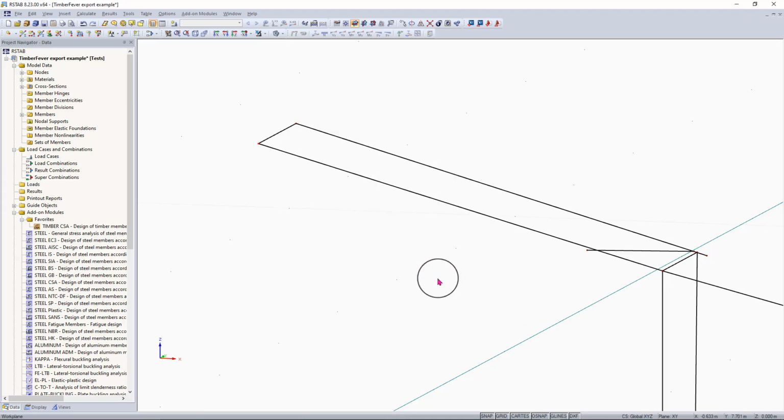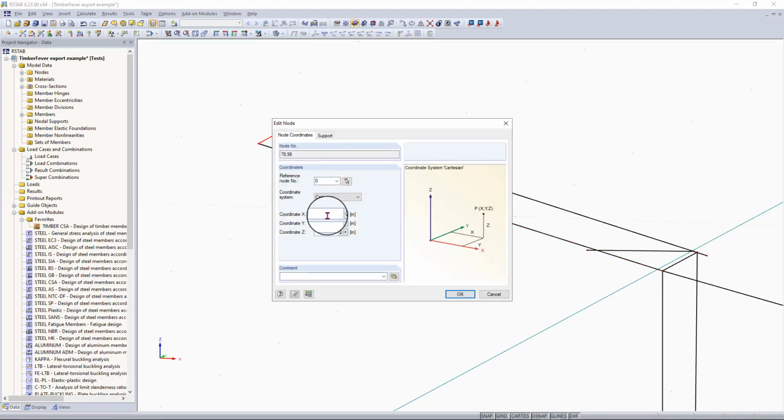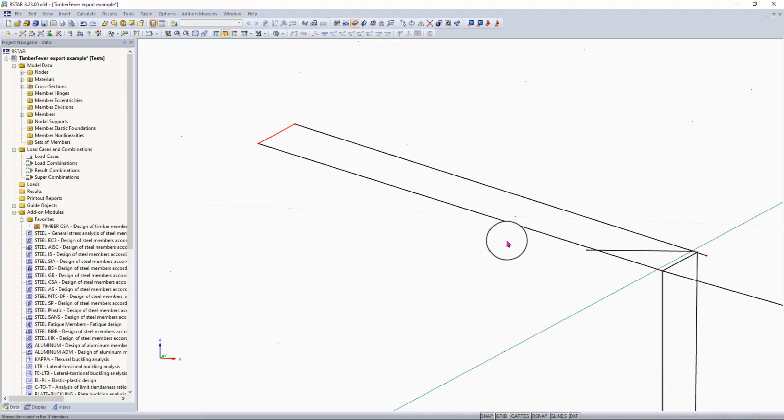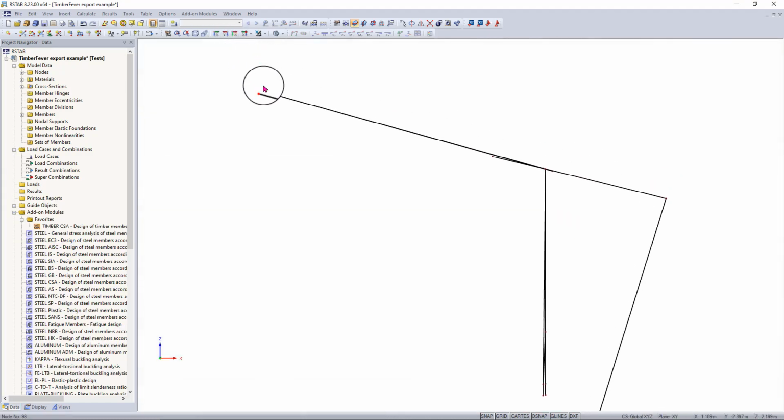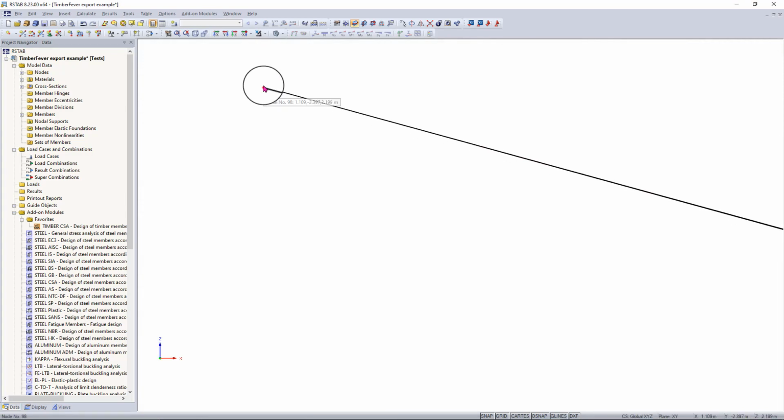We can click OK. Then what we can do is drag from left to right to highlight two of these nodes. We can double click on them, and then we can type in those coordinates. So 1.109 for the X and 2.199 for the Z. So now if we look at our view in the Y direction, we can see that our nodes are completely lined up along the y-axis in the Z and X direction.